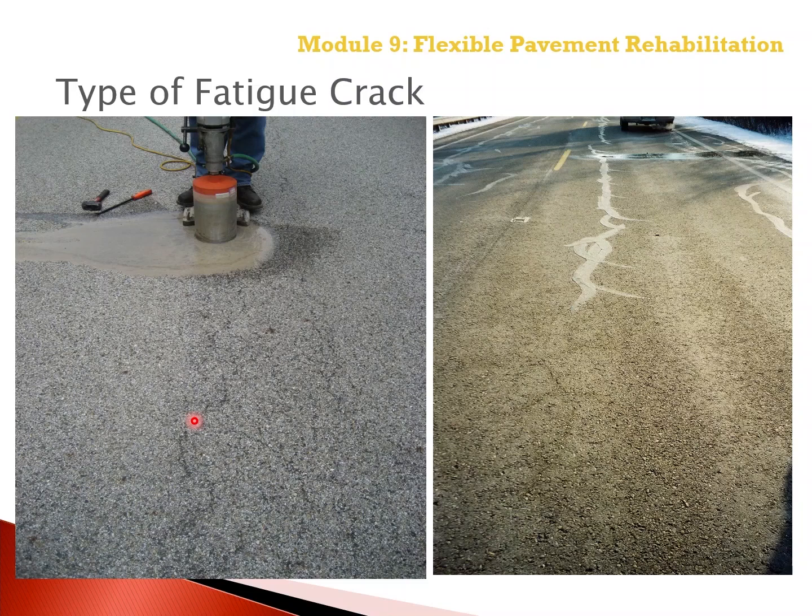So if we did a distress survey, or input level 2, and assume everything is equal for these two projects, then the amount of fatigue cracks or damage index predicted for the existing asphalt layer should be the same, based on the distress surveys of total bottom-up, alligator, or fatigue type cracks.